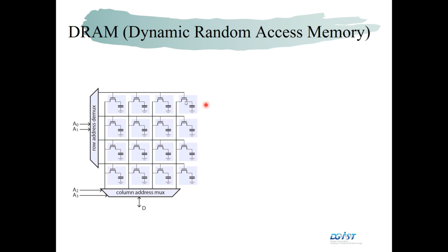Okay. So here in the DRAM, we have 16 same elements. They consist of one capacitor and one transistor. We call this the 1T, 1C model. So here this transistor is kind of a switch. And if you close this switch, you may store the charge in a capacitor.